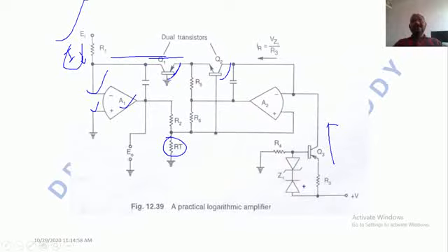As we know, in ideal characteristics we can replace the diode in forward bias with a short circuit. In reverse bias it is an open circuit, but here the positive terminal is connected to the anode of the diode. That's why I am replacing this with a short circuit. Now, how much voltage drop is there across the resistor R3? It is the Zener voltage, the voltage drop across the Zener diode, because both are in parallel. How much voltage is appearing over here?